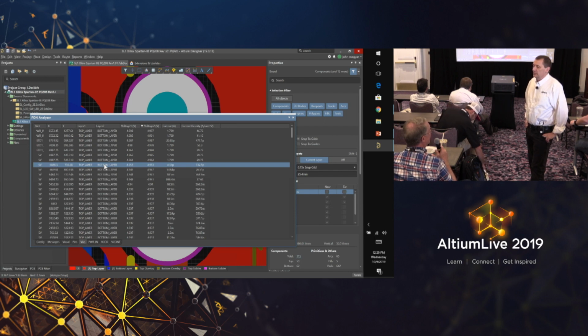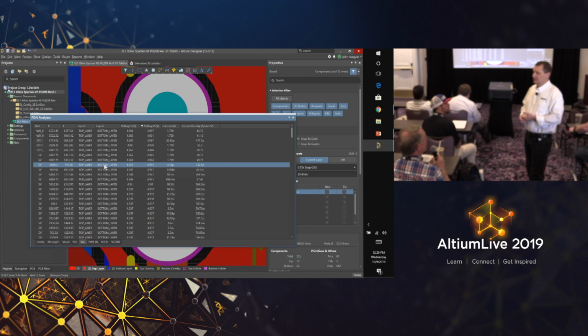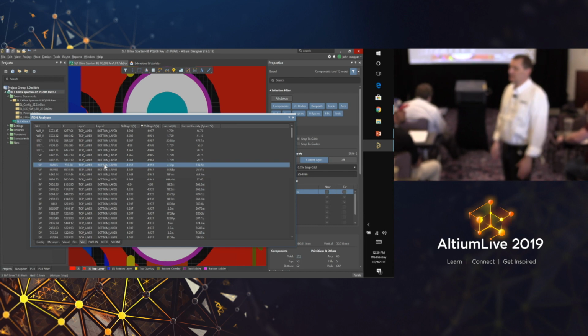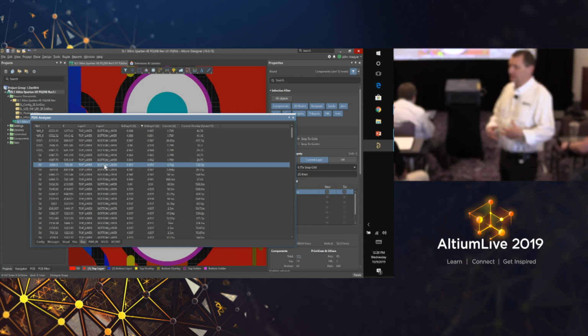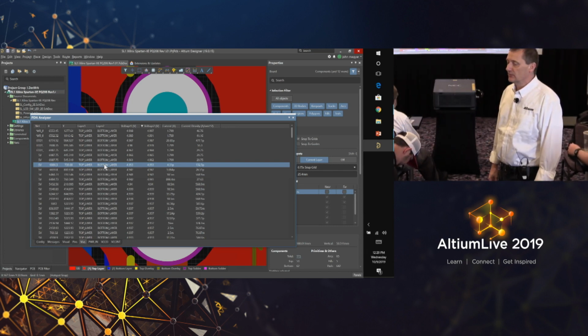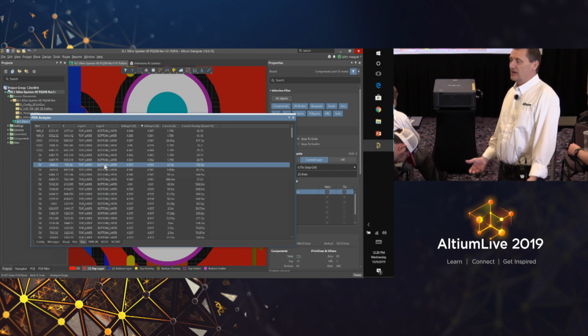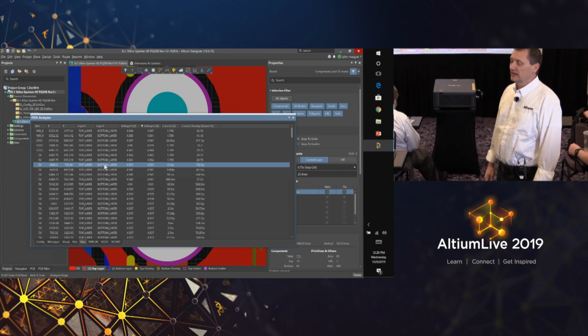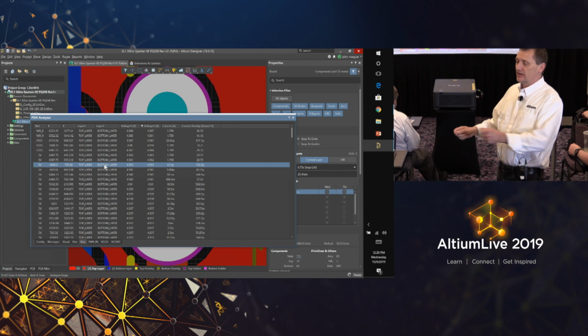It will miss reactivity because it is static. It's not simulating in time and with all of the behavior of every semiconductor. So you can create a worst case load, and it will determine the resistance between the two, and then that's how it's figuring out voltage drop and current. So it is that basic. So you're not going to get dynamic spikes or anything like that. But if you anticipate what could be the highest corner case, can my design handle that, then that's very easy to describe. And then you save that as a configuration.